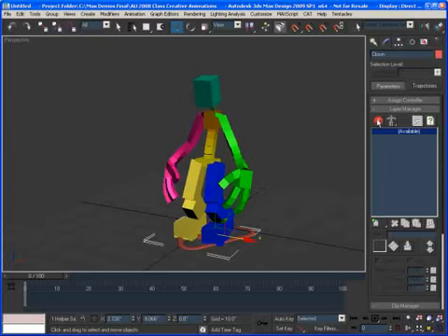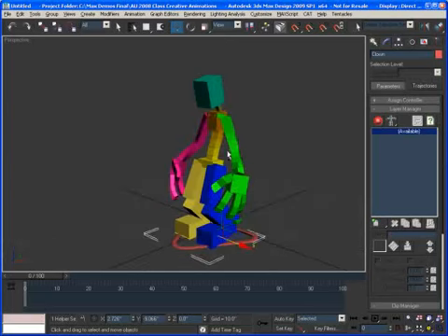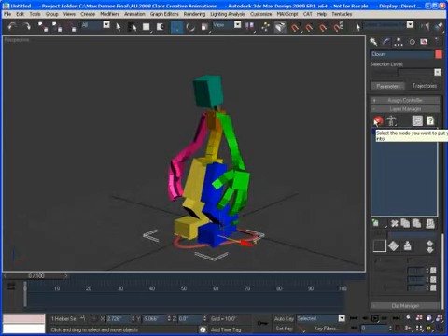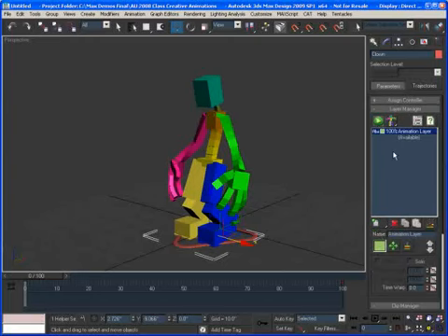That's the pose or the setup that you're going to skin to, and then you're going to start animating, and those animations will be done on top of the pose, and you can go back to the pose whenever you want. So right now we are in setup mode, and it's very important when you're not animating to be in setup mode. If I press this button, I'm not able to go into animation mode, and the reason is that I have no layers. I'm going to talk about animating a bit later. But if I want to go into animation mode, you see where it says available, I'm just going to click on that, and you've got all sorts of layers we're going to talk about a bit later. So if I go here in absolute layer, you'll see that now I can click on this and I can go in animation mode.